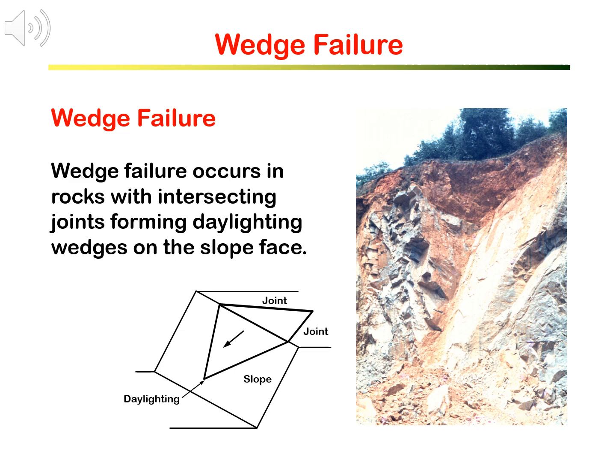This type of slope failure is wedge failure. It occurs on rock slope when daylighting wedges are formed on slope by the intersecting discontinuities. Similarly, a daylighting wedge is a wedge with its bottom end appearing on the slope face. This is in fact the intersecting line of the 2 joint planes daylights on the slope.